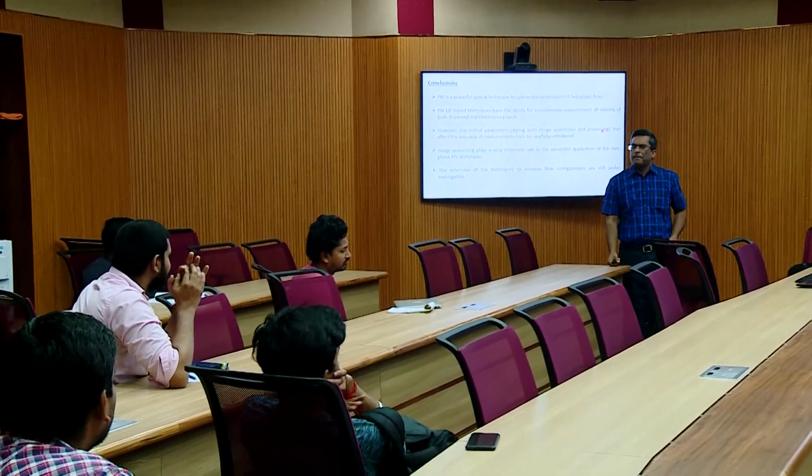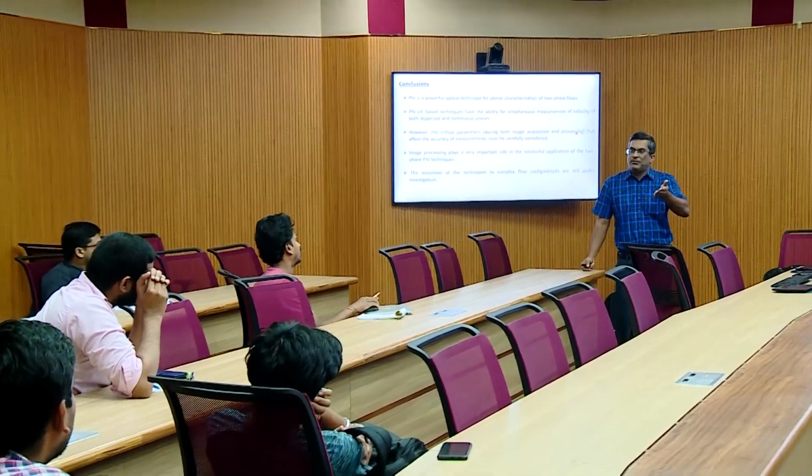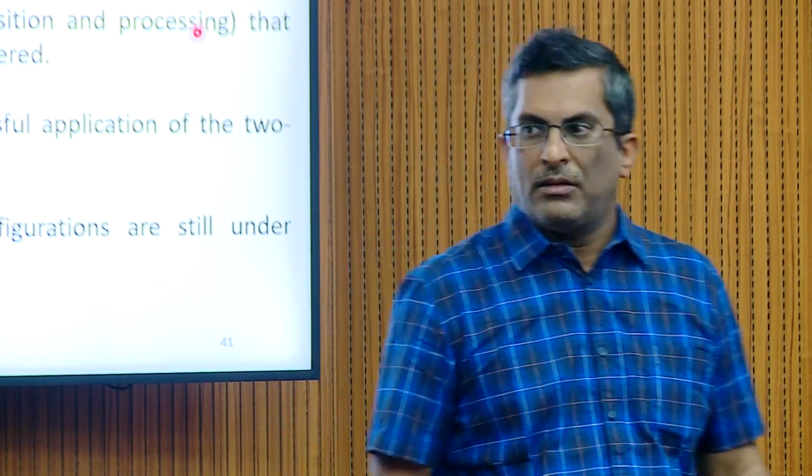Is it possible to do it manually? Sometimes the laser output can be connected to the cameras, but usually you won't be able to control it. It is not like we just want to synchronize once. We need to be able to adjust the delta t and the frame rate. All these parameters you should be able to adjust, and it can be easily done. Even using Arduino boards, people have done it, at very low cost.